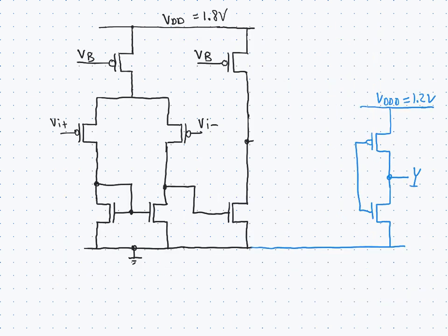Now, if we have the situation where we have different analog and digital supply voltages, we will need to make sure that the bias condition for the analog gain stage sits somewhere in the mid-range, or in the transition region, for the digital inverter. If we have, for instance, a 1.8 volt power supply, then the expected value for the output of stage 2, so Vout2 in the bias condition, would be roughly, let's say, 0.9 volt. This would be a reasonable expectation.